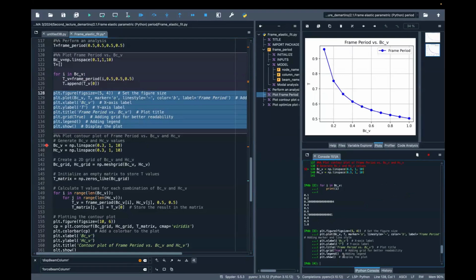You can see here that you have the base of the column as a function of the period. Obviously, in this case, if you want to have a structure with a period 0.6, you can read on this diagram, for a structure with 4 spans, 4 base, and a height, one side of the column 0.5, and beam 0.5 by 0.5, you need a value of the side of the column of around, I would like to say, 0.45. Something like this. Similarly, if you want a period of 0.5, you need 1 meter, okay? That's a very simple way to optimize your problem and try to understand it.